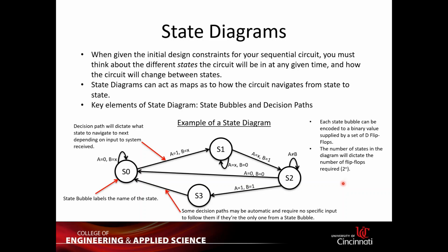If you have 3 states, sometimes you have a 3-state system, then you still need 2 flip-flops. So the number of states has to be equal or smaller than this number.